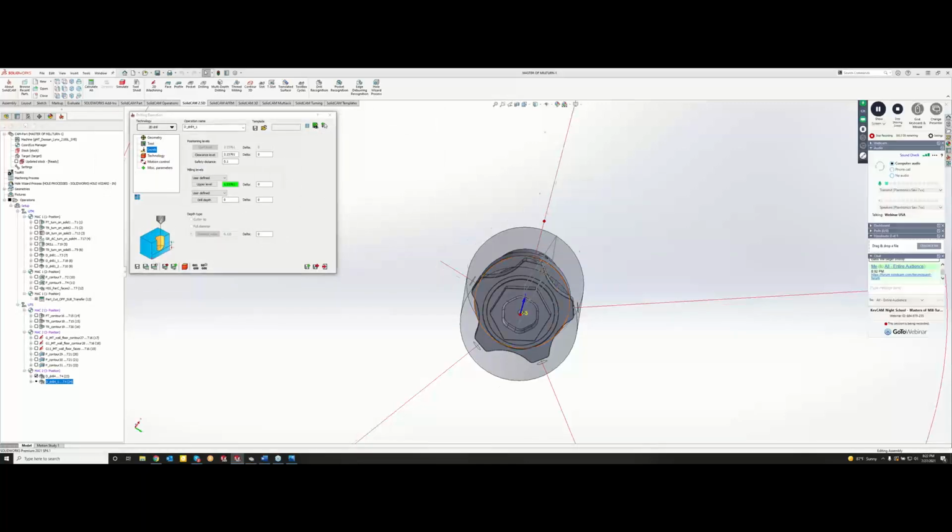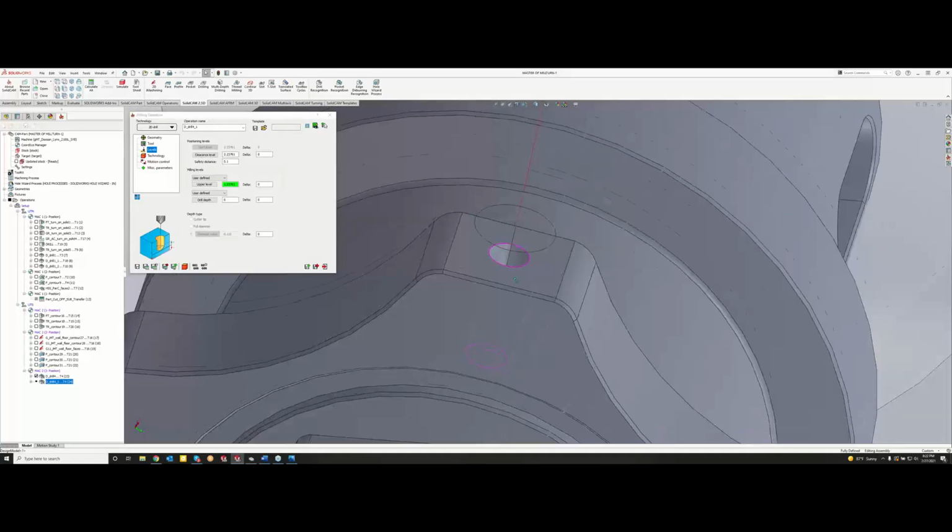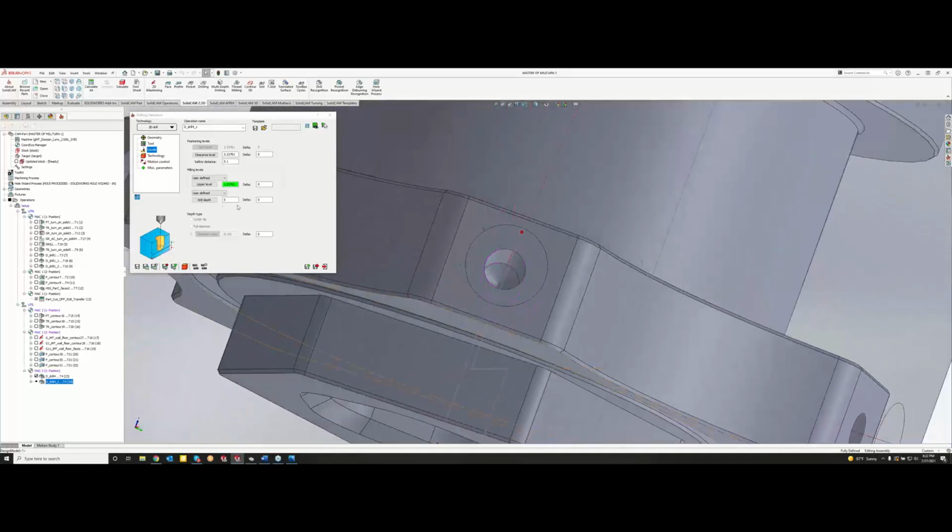Levels still are going to be the same, except I'm not going to go based off of diameter now. I am going to do based off of drill point. So now my drill depth is going to be down to my drill point there. And it's going to actually, I'm sorry, let me rephrase that. Since I picked an end mill, which is a flat bottom end mill and not a drill bit, you'll see that it doesn't give me the options to go off a cutter tip or full diameter. So when you're picking your levels, I don't want to pick the point that I come down to here. I want to pick right where it comes down to where the flat is. So hopefully that makes sense, because we've got a flat end mill and we want the diameter to reach right there. Okay.